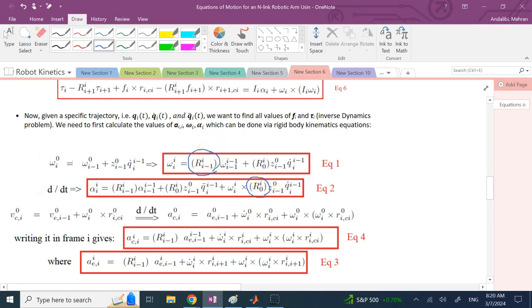And these relative R's, if you remember, what are these? These are those A matrices that we have in DH, correct? Now, of course, this is A_i inverse because R of i in i minus 1 is A_i. Remember, this A is a 4 by 4, so what I need is only the 3 by 3 minor of it. So here I have to say this is the 1 to 3, and 1 to 3, and then of course transpose.